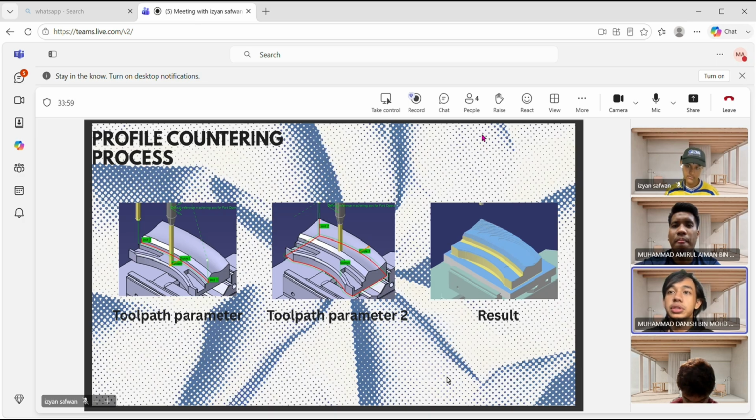Compared to conventional machining, this strategy provides better geometry accuracy, smoother surface transitions, and reduced scallop height. The simulation also confirmed that the tool followed the programmed toolpath smoothly without any collision during the flank contouring process.